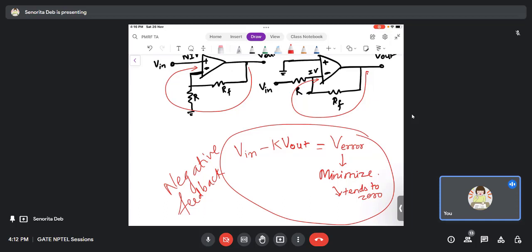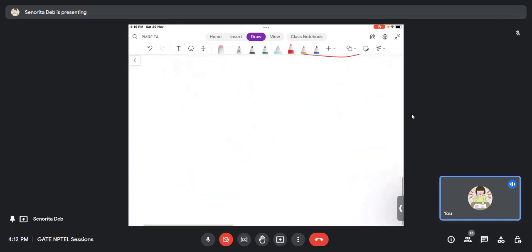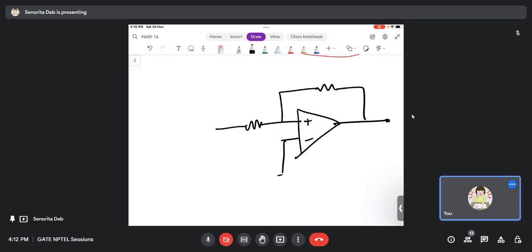That is the concept of positive feedback or oscillator. They are also called regenerative feedback, because you are regenerating the input. Even if you remove the input, the small output which was earlier generated will treat itself as the input and keep on increasing. So that is positive feedback.